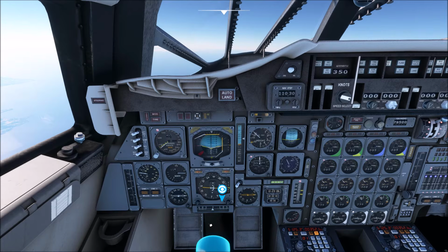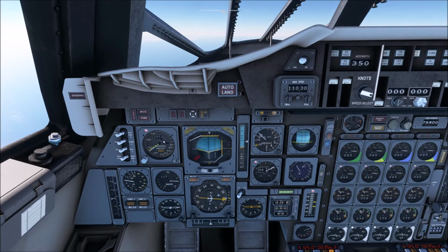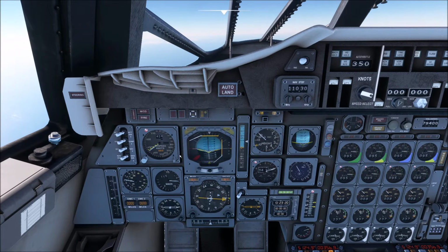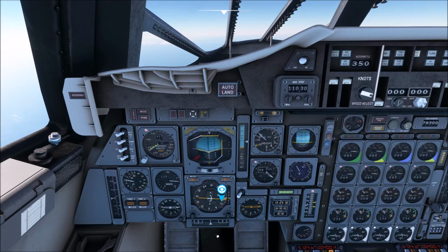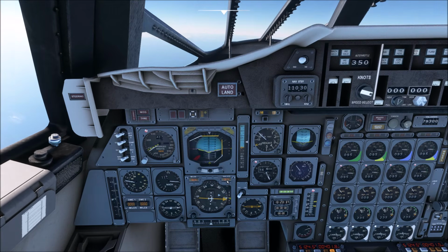And here's another interesting one for people who want to learn. 422 knots indicated, but look at this, 667 knots ground speed. That's because even though we're accelerating, as the air gets thinner at higher altitudes, indicated airspeed readings reduce, but ground speed increases. That's the difference between ground speed, Mach, indicated, calibrated airspeed, true airspeed. They're all different depending on what you're trying to measure. That's the one you would measure our ETA into New York on.